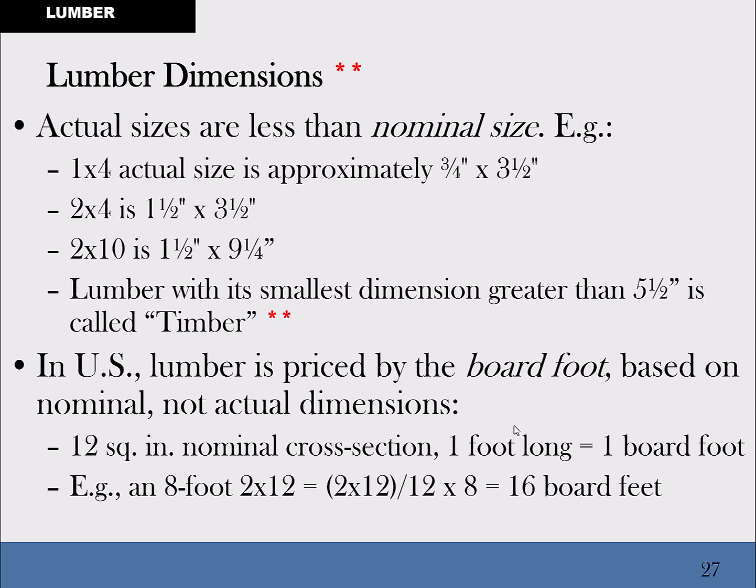And at the other end, you might be reaching closer to 11 7/8 or almost 12 inches. They can vary that much from one end to the other end of the board. So it's not as precise, but for 1x4, 2x4, 2x6, it's very precise, which makes some great lumber to be framing up a house with.